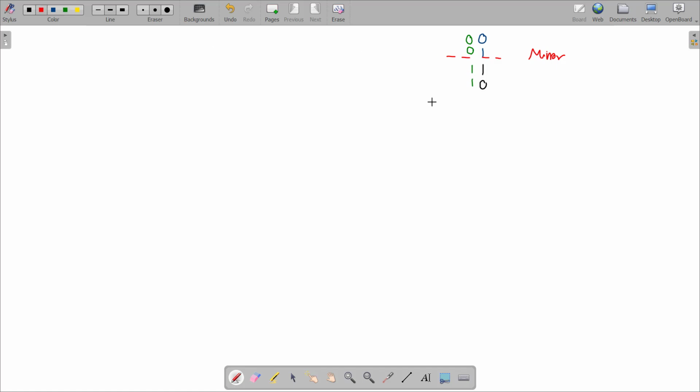If I want to continue, again, I mirror these 4 codes. If I mirror these 4 codes, I will have 0 1, 1 1, 1 0, and 0 0. Again, according to this concept, this is the original code. Add 0 to the original code and 1 to the reflected code. Now, if you look here, I could produce the gray code with 3 bits.